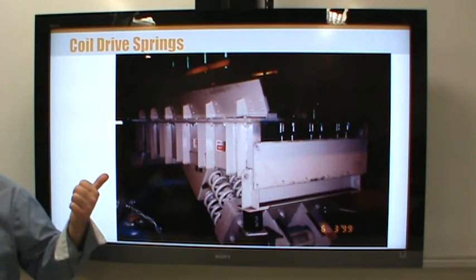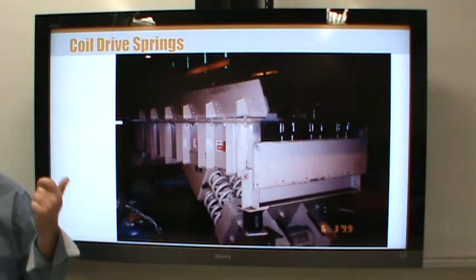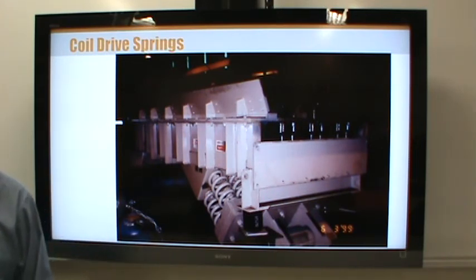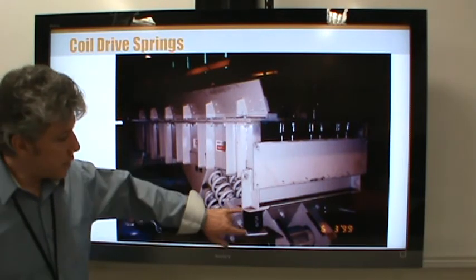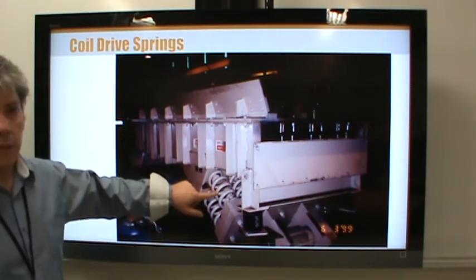Linearity is one of them. Okay? Rubber springs are not linear. There's another big difference though. Amount of deflection. The spring constant range can be different, but these are fairly thick springs. I mean, this kind of connects to thermo, but I would say with the coil spring, there would be less energy lost to thermal energy, whereas in the rubber block, all of that energy would be absorbed and then given off as heat, whereas in the metal spring, it would just be transferred from one to the other. That is a huge difference. That was the one I was going for, is that this type of spring is a lossy spring, whereas this one doesn't lose as much energy.